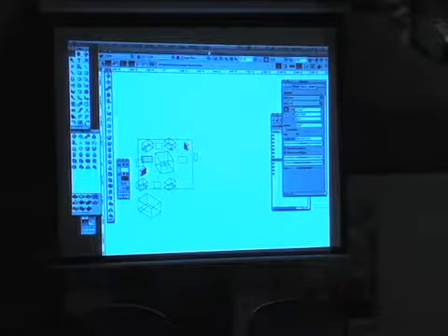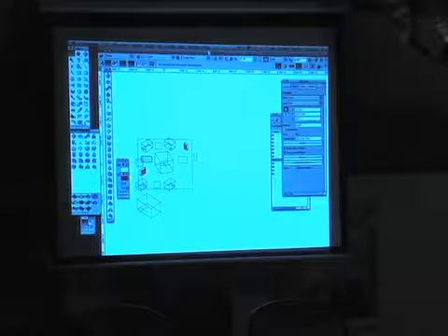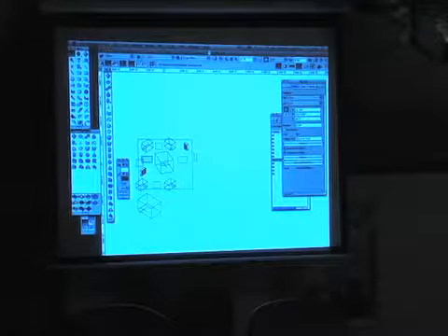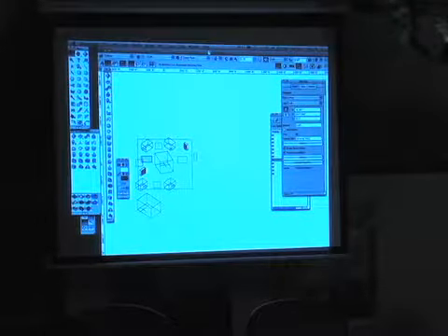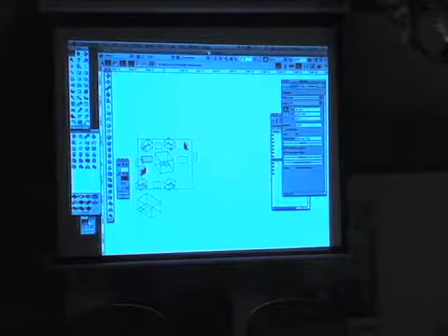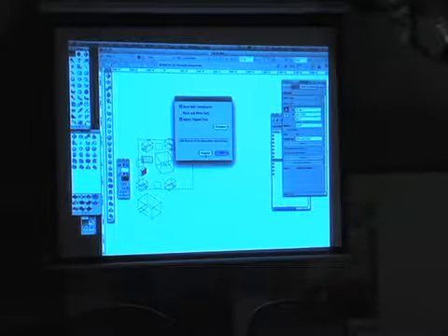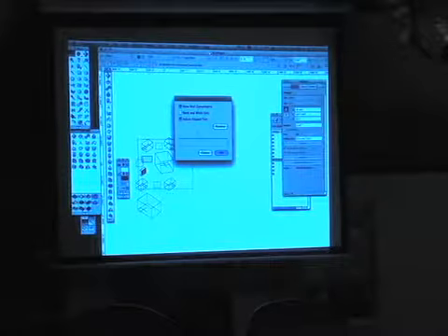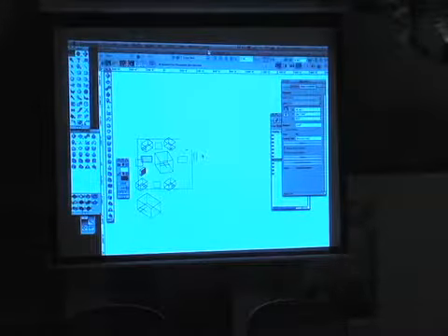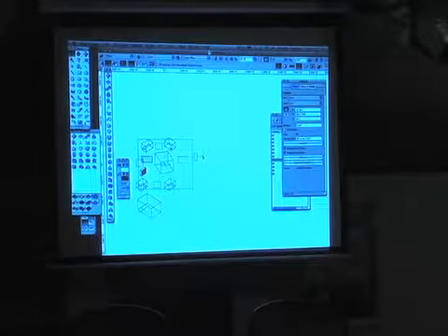But in a sheet layer viewport, we're able to create a viewport, then change it on the fly as we're in that sheet layer, and duplicate them and change our top plan to a front plan. In design layers, as far as I know, even under advanced properties, I couldn't find anything. And is it updating automatically because it's in a design layer, without you having to hit an update button?